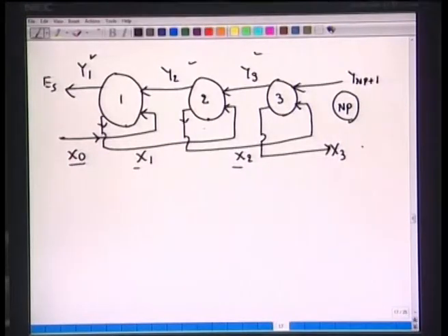Let's focus on this. Overall, it's still a counter current process. All we have done in stages 1 and 2 is make sidewise entries, right. So for an individual stage, somebody can look at it as if it's a stage with a co-current process. This stream enters with the composition y2, leaves with y1, and this stream enters with x0 and leaves with x1.